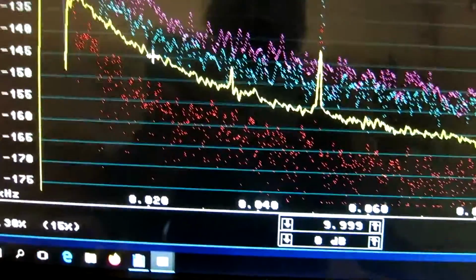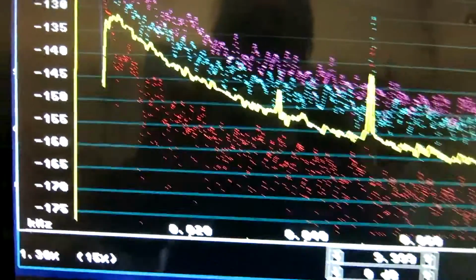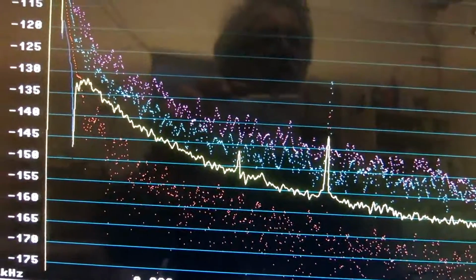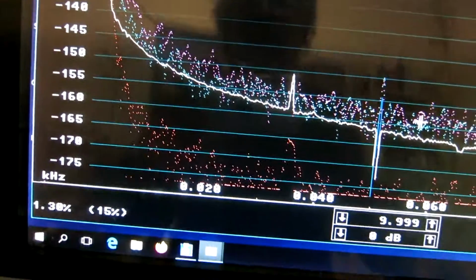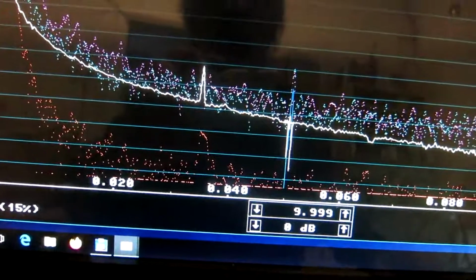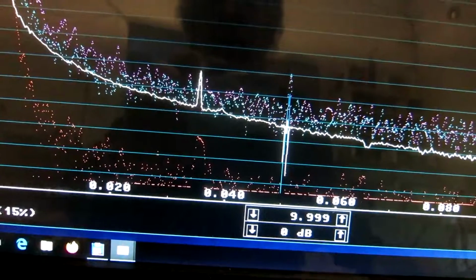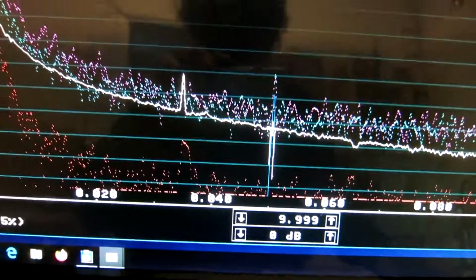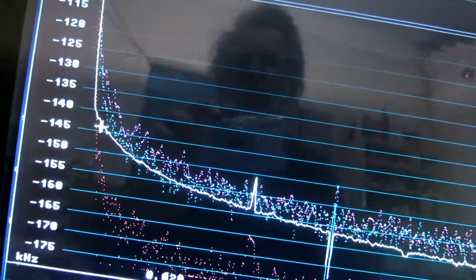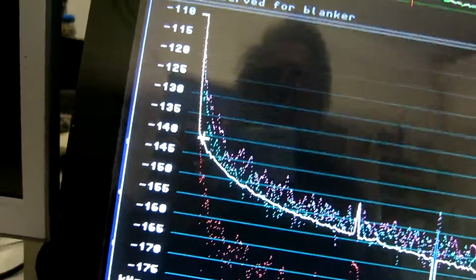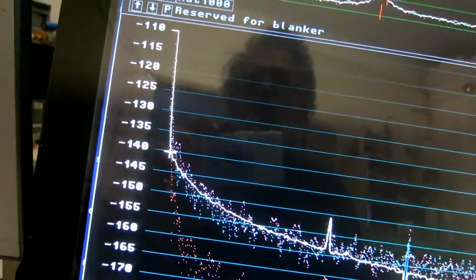I will take down the values down to 10 Hertz from this measurement, and also for the amplitude part, which comes soon. I have clicked for A and I have to wait. Here we have at 50 Hertz it is minus 162 approximately. I had noted 162.0 before. And here I don't see this artifact from frequency pulling, but something happens below 4 Hertz or so, I think.